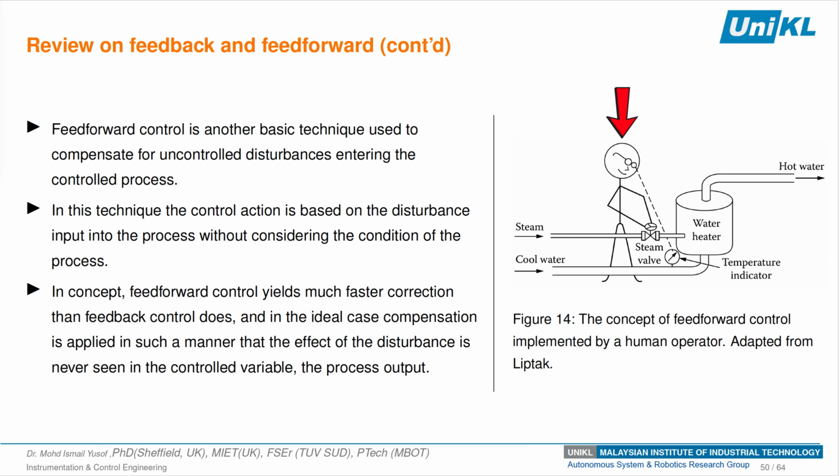A skillful operator of a direct contact water heater could use a simple feed-forward strategy to compensate for changes in inlet water temperature by detecting a change in inlet water temperature, and in response to that, increasing or decreasing the steam rate to counteract the change. This same compensation could be made automatically with an inlet temperature detector designed to initiate the appropriate corrective adjustment in the steam valve opening. The concept of feed-forward control is very powerful, but unfortunately it is difficult to implement in